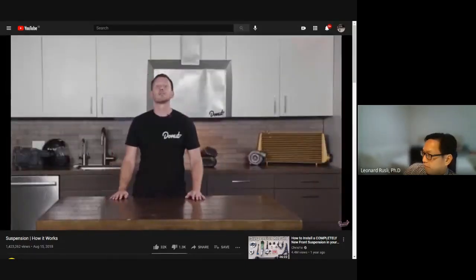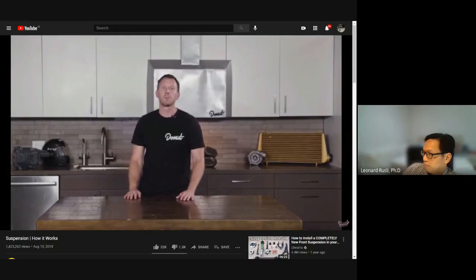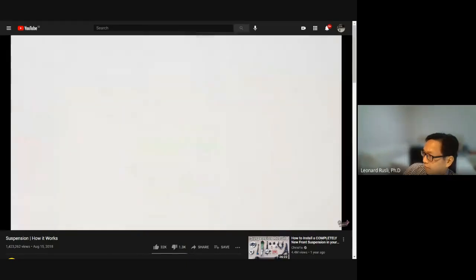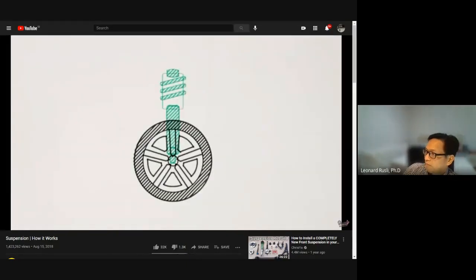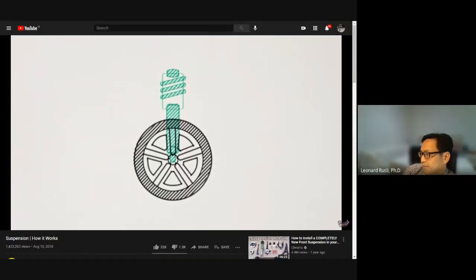The Mac Daddy of struts is the McPherson strut, invented by Earl S. McPherson. No one knows what the S stands for except for Wikipedia, which says it stands for steel. Cool. The McPherson strut consists of a single control arm and a strut assembly, which allows tire and wheel to move upward and downward. Its design allows for a reduction in a number of parts, lowering unsprung mass as well